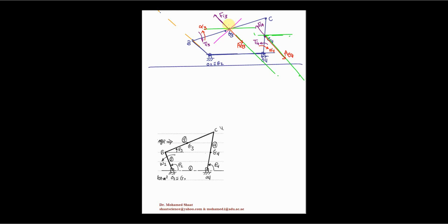Then over this line, you're gonna measure the H value that we calculated for link number 3, which we got as 4.4 millimeter. And remember that we're already working at scale 1:1. This is the scale that we already use for this graph. It means that the 4.4 millimeter will be drawn as 4.4 millimeter. So your objective is just to measure, starting from point G3, either up 4.4 millimeter or down 4.4 millimeter.